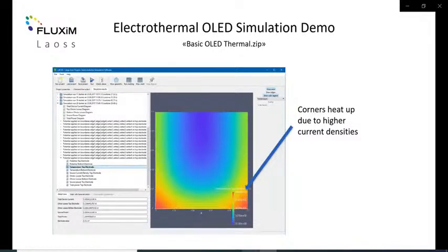You can see clearly that the temperature is highest in the corner toward the center of the panel by about 40 degrees Celsius. One could also now easily play around with some parameters in the simulation to check how this deterministic effect could be decreased.